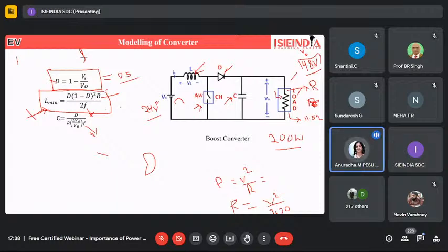How do we choose F? Simply, you have the catalog of the different switches. Depending upon the frequency that the switches provide, if you see the MOSFET or IGBT catalog, they list this much frequency. Depending upon that, we choose it.